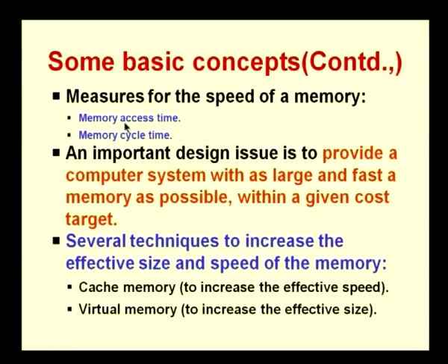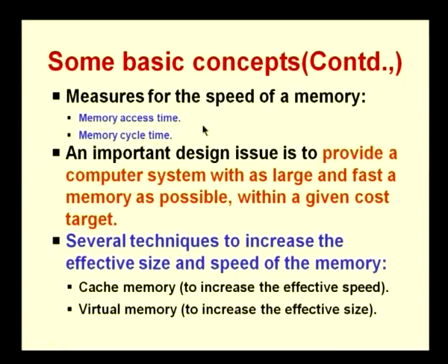In fact, when we are reading from memory, access time is specified with respect to the time taken from when the address is placed until the data becomes available. When you are doing a write operation, we need to take other things into account, because the address will be specified and the data will be specified. You will give a write control signal to memory, but your data will have to be present at the interface for quite some time before the data actually gets written into the memory. We normally refer to that as setup time, and you have to hold it in that place for some time. We call that hold time.